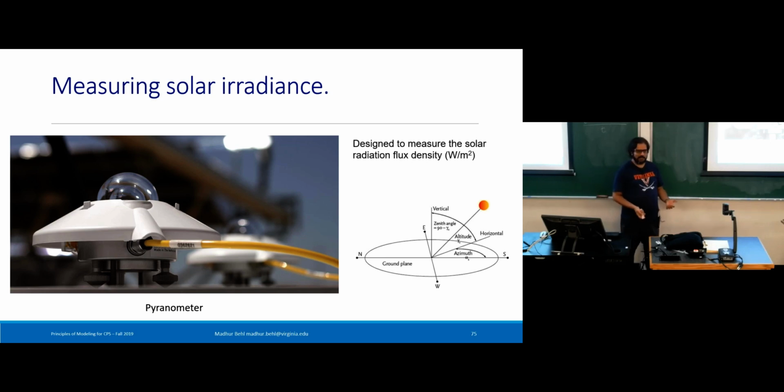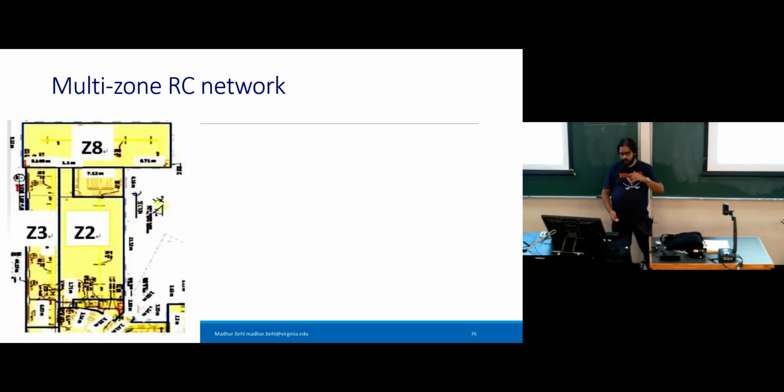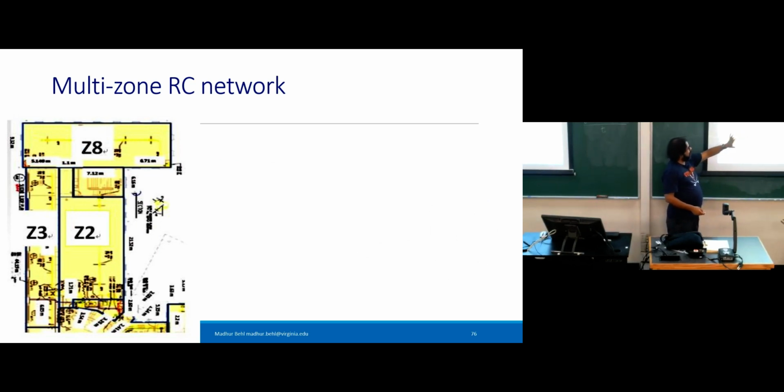Other things are easy to measure. Temperature is very easy to measure. So if you go back, this ugly picture is the floor plan of the zone that I had to model for that building. This is the wall which had those 8 windows. This is that porch area, and there was an adjacent zone over here. I wanted to show you this picture because when we were talking about how you model a building, the first step is you get this geometry or building information. And this is what it looks like. This is literally the scan of what we got when we had to model the building.